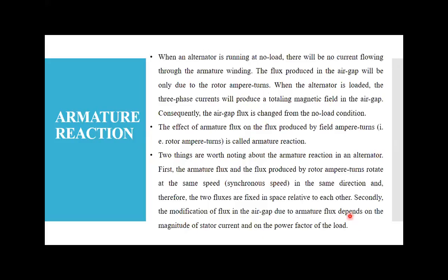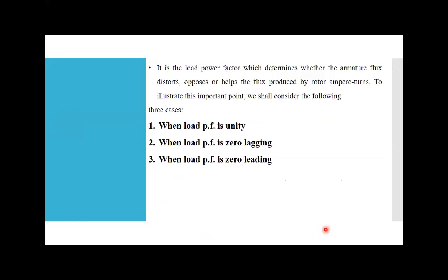So the air gap flux depends on the magnitude of the stator current. Stator is nothing but our armature. So the magnitude of the armature current, either 10 ampere or 100 ampere or 1000 ampere. And secondly, the main important factor is that it depends on the power factor of the load. So this is about the armature reaction.